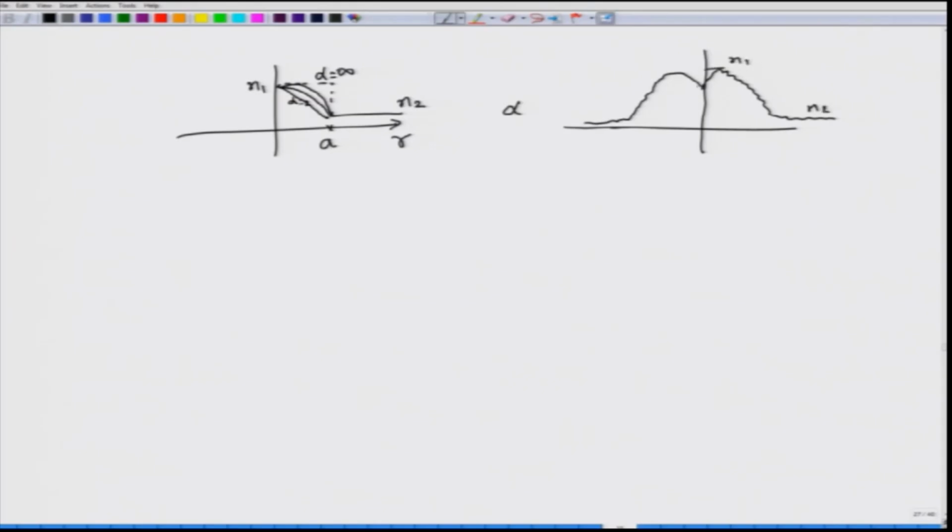Of course, this dip is unavoidable, as I told you, because of the manufacturing problem, and also notice that the refractive index is not going like a smooth curve, but rather has jagged edges. That is because the refractive index profile, despite whatever manufacturing improvements we have made, is not really giving you a smooth profile. Those surface roughness, if you were to examine them, would give you a jagged refractive index profile.